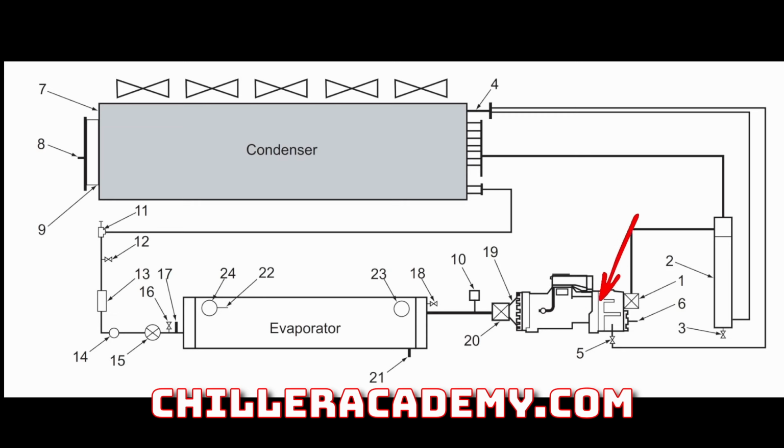What this one compressor is able to do, and this can be done up to several hundred tons, 3, 4, 500 ton machines with just one large compressor, not an RTAA, but an RTHD can handle those kinds of loads. It's a very, very large compressor. And with our ability to move that slide valve, we're not having to slow the motor speed. It's not doing anything in this particular case, even though it could be. And we'll talk about variable speed in a minute. But that slide valve, from a basic compressor design, is able to have immense control on this compressor's capacity in order to just maximize efficiency.